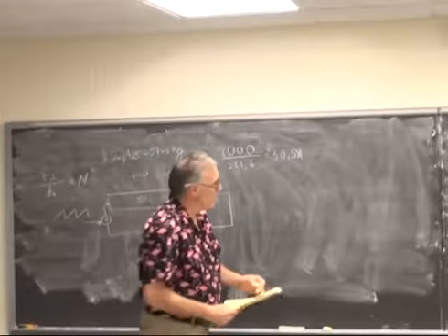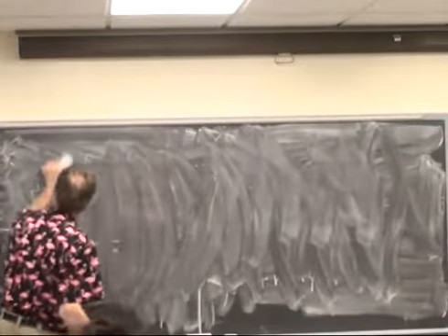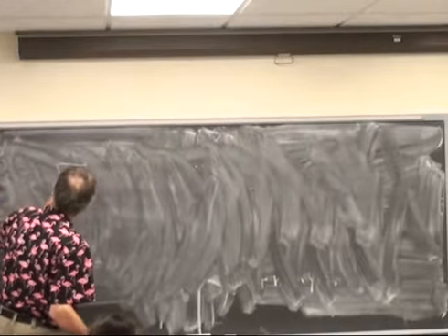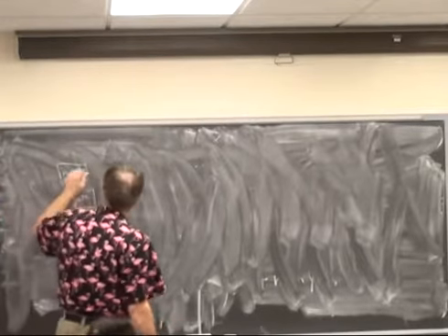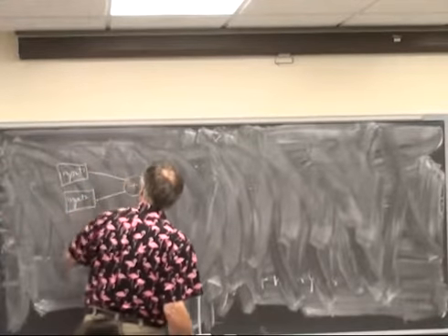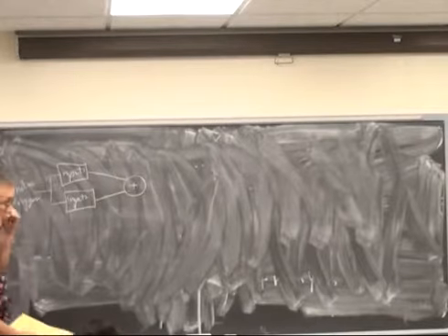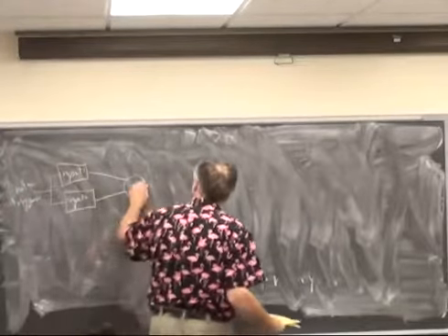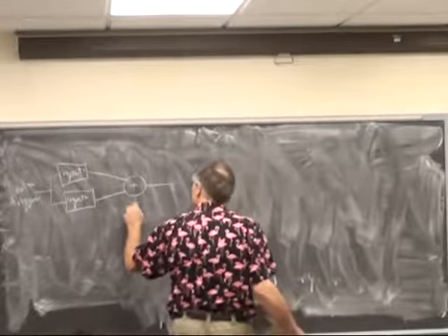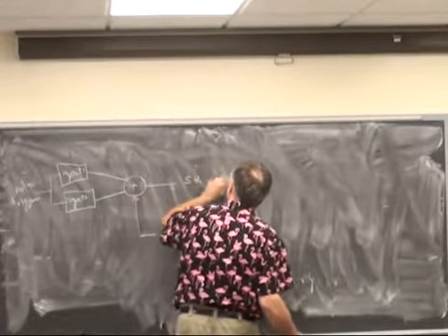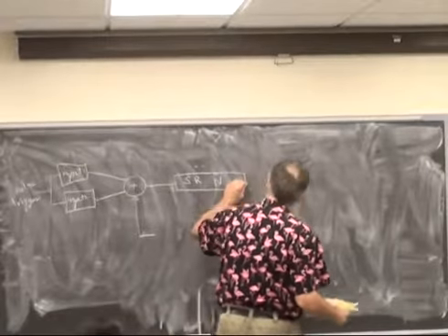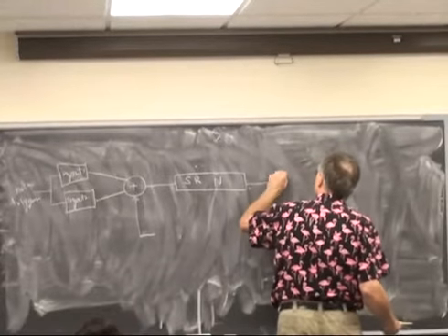So the full Karplus-Strong, with everything added, and this is really due to Julius Smith at Stanford, is you have a couple of inputs, as many inputs as you want, which are then added into, and there has to be some, of course, note trigger here, which represents the t equals 0 time, which is added into a feedback coming from the shift register, which gets shifted out, and in general we're going to have an output filter here.